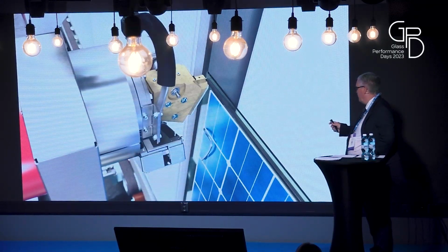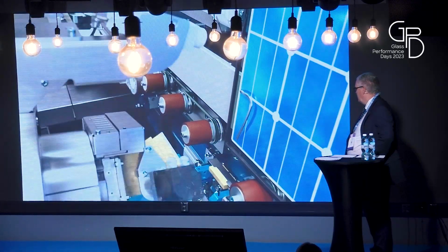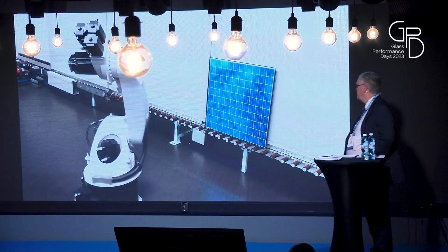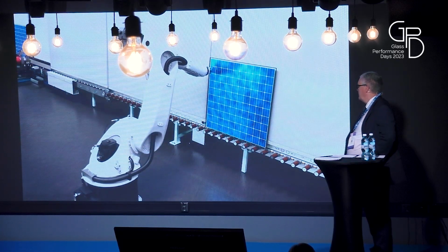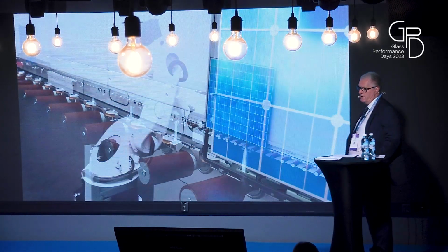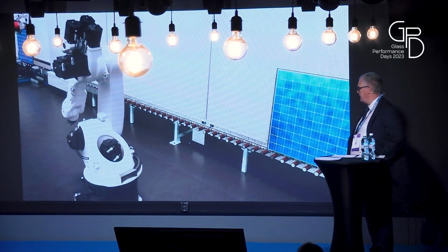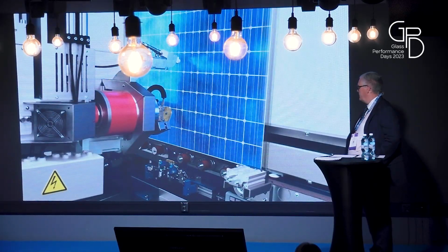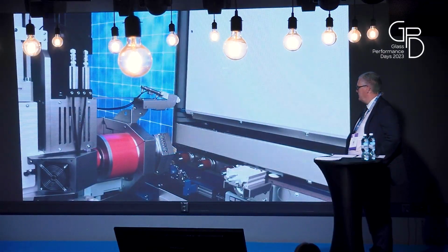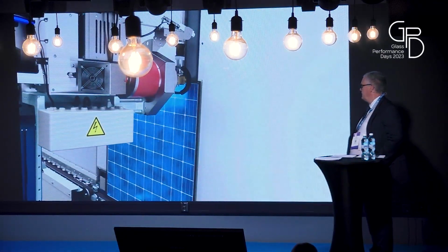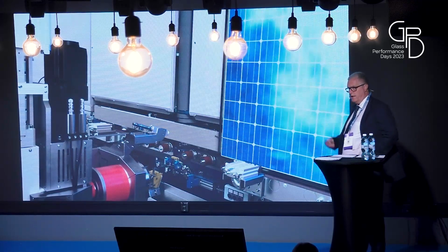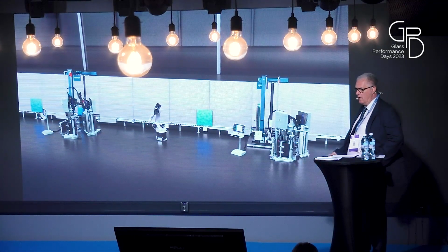First of all, the first application is made, and then the electrical contact will be taken out by a robot system. And with our multi-layer technology, we have the possibility to encapsulate this electrical contact by a second application, which takes place with a second applicator here. Now it's totally encapsulated, and this functional glass can then be assembled together as an IG unit and installed as a PV module in houses.